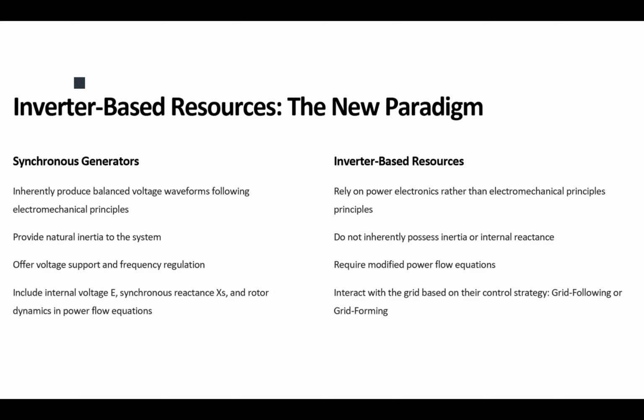If you wanted to find this out mathematically through the equations, these internal voltage and reactance would show up in the differential equation that we saw before, which described one of the parameters, inertia, another parameter, the damping factor, and another, the external force that we have. We already went over that briefly. So these are the parameters that model those physical aspects.